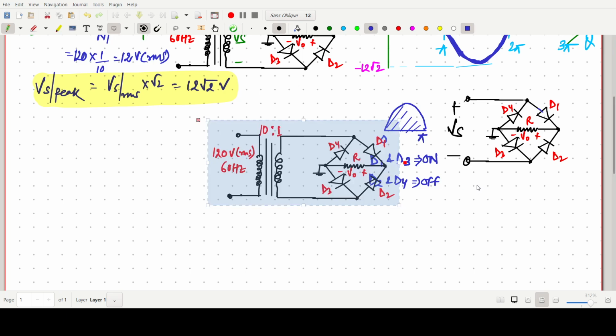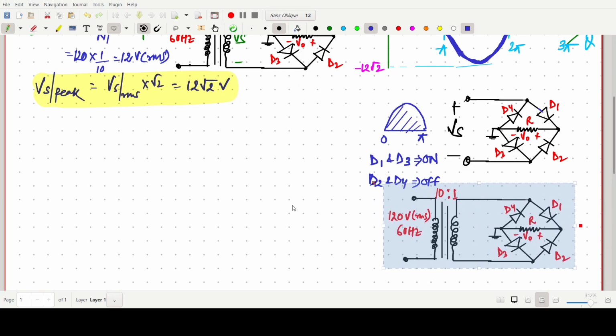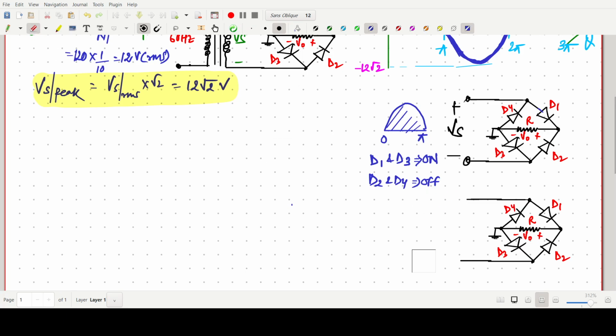So this working I'm going to discuss will take two or three more minutes, but I will complete that one first. Here, for the positive half cycle, this D1 will be conducting, so we can put this as 0.7 volt, and D4 and D2 will be off.